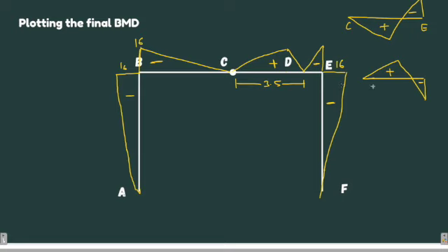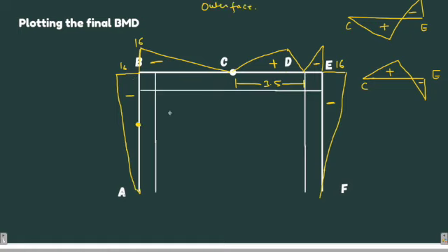So there are various formats of drawing the bending moment diagram. Don't get confused. The convention which I am using is that I am drawing the bending moment diagram for the outer portion of the frame. You can also draw it for the inner face.